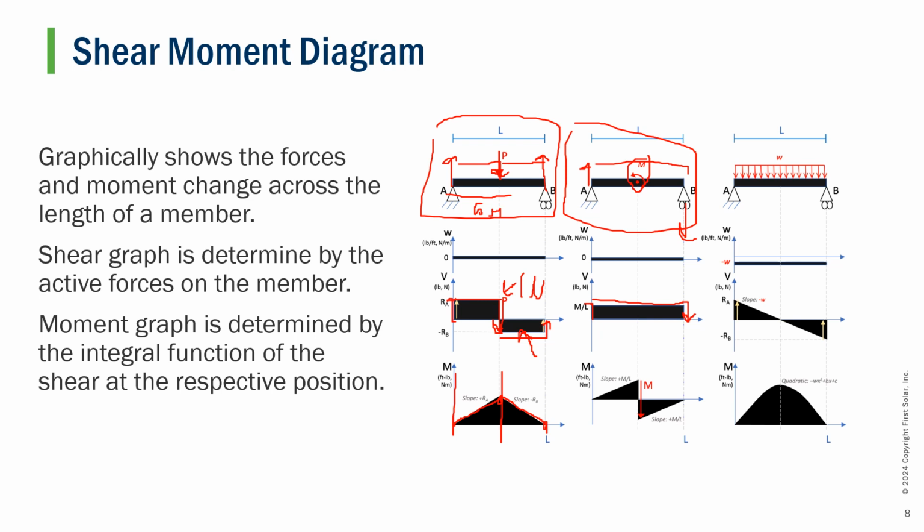will do to our moment diagram is, again, we take the integral from A to B, which will result in this slope seen here on both sides of the moment. However, this negative moment will offset or adjust the center moment diagram. Again, going from 1 to 5 or whatever value this may be, subtracting the total value of this moment, going down to this value, and again writing up the slope to a total value of 0.